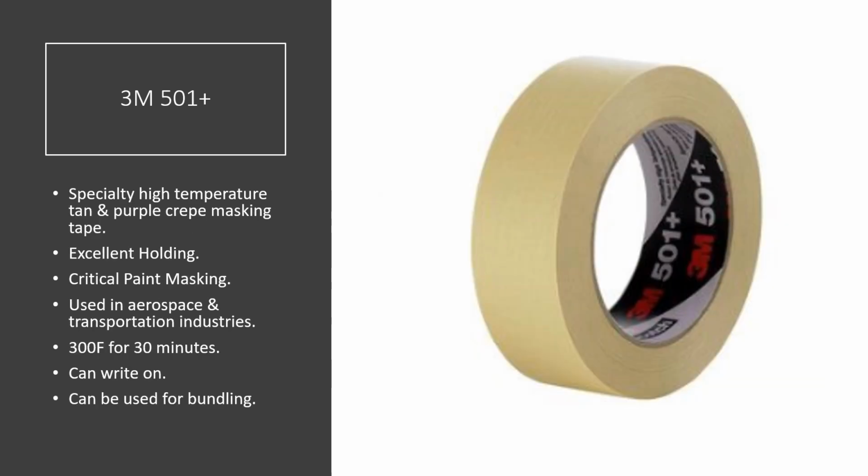So if you're looking for paint masking and need some critical line masking, this could be a good go-to for that. 3M 501 Plus is the highest engineered masking tape out of the 3M Masking Made Simple portfolio. It's going to have your highest temperature resistance at 300 degrees for 30 minutes. Similar characteristics to the other few that we mentioned, can be used for bundling, can write on. Typically see it in aerospace and transportation industries where you need that high temperature resistance and that critical paint mask sharp line.